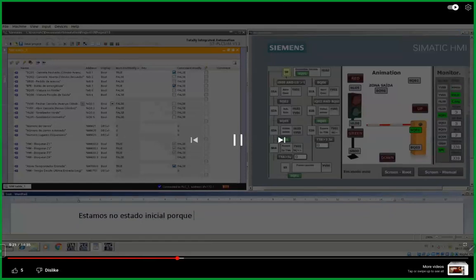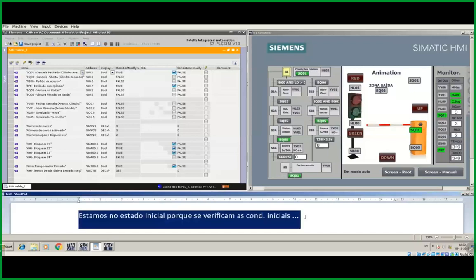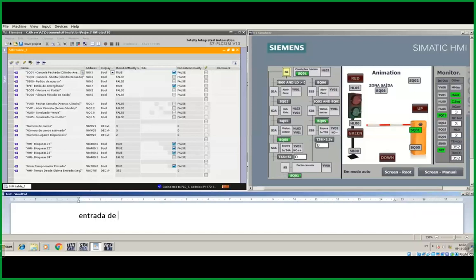So here's the graph set. You can see that right now we are in state S0 because the S0 box is yellow. And we have several inputs and outputs. Those are these little squares which are green. That means they are on. For example, I just turned on ST01. Okay? And you just switch the color. Then when you start going through your graph set, so going from state S0 to some other state.